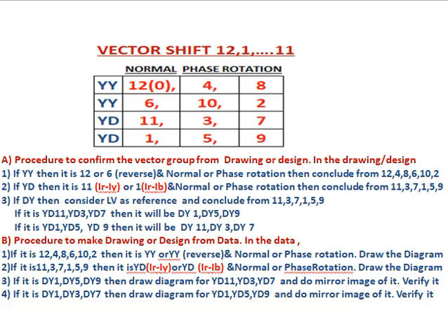Then second YY. This is one Y connection is reversed. That is, instead of A1 A2, it is A2 A1. Then it is reversed. So YY reversed normal is YY6. If any phase rotation happens, then it is YY10 or YY2.